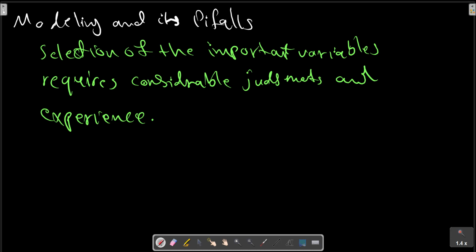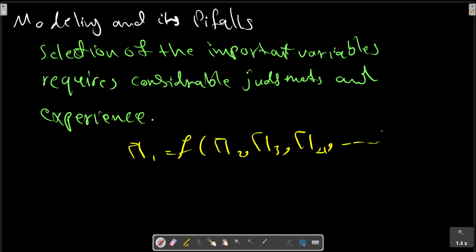With sufficient testing, the model data will reveal the desired dimensionless function between variables with pi functions. With this equation available in chart, graphical or analytical form, we are in a position to ensure complete similarity between model and prototype. A formal statement will follow.